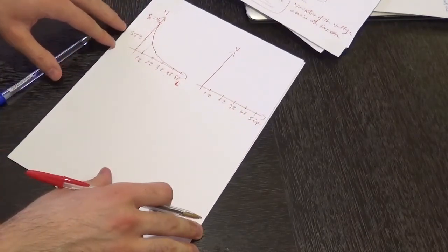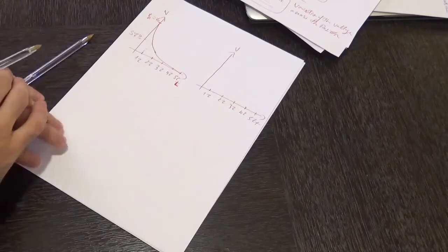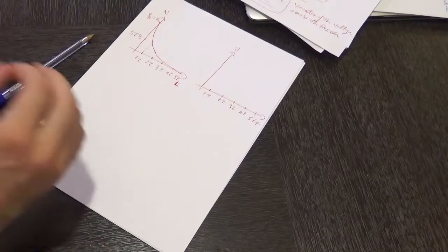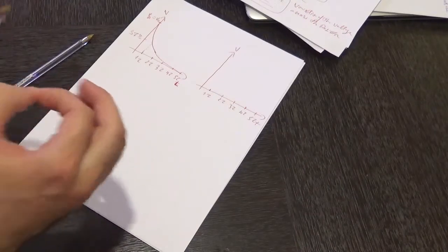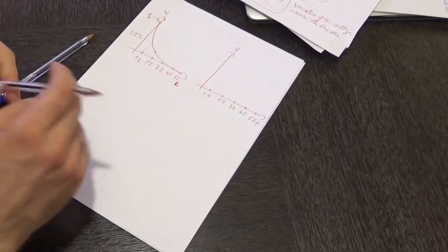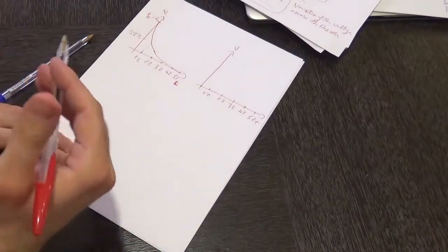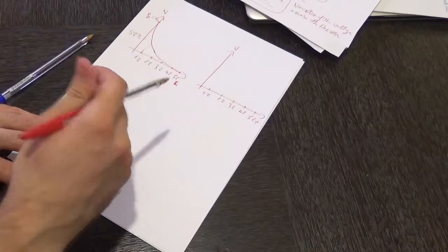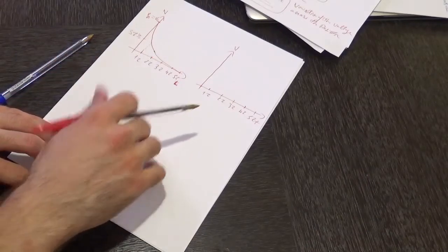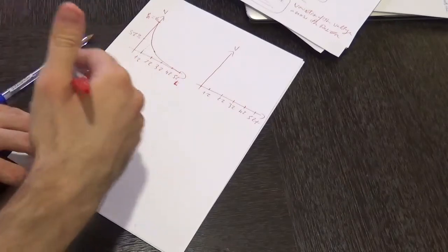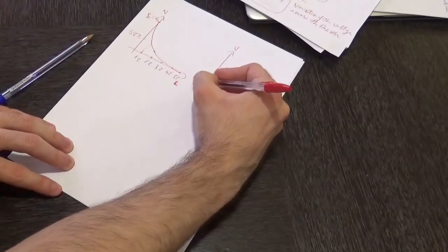Now regarding the capacitor, it's in the opposite manner of the resistor. We are starting at a value of 0 volts across the plates of the capacitor. So we are starting from the origin. And then the capacitor starts to store charges on its plates, and therefore the voltage on it is going to increment, but it's going to increment exponentially until the capacitor is fully charged after 5 tau.